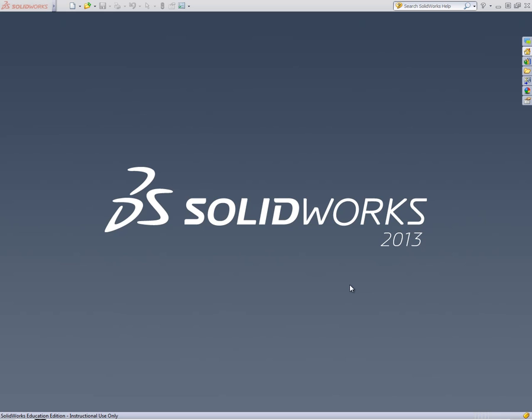Up to this point, for each one of the modules, we have started a new drawing or we've opened an existing drawing by using the new or open icons to the upper left. For this module, we will move the cursor to the upper right corner, over the design library icon, which looks like little books stacked up.